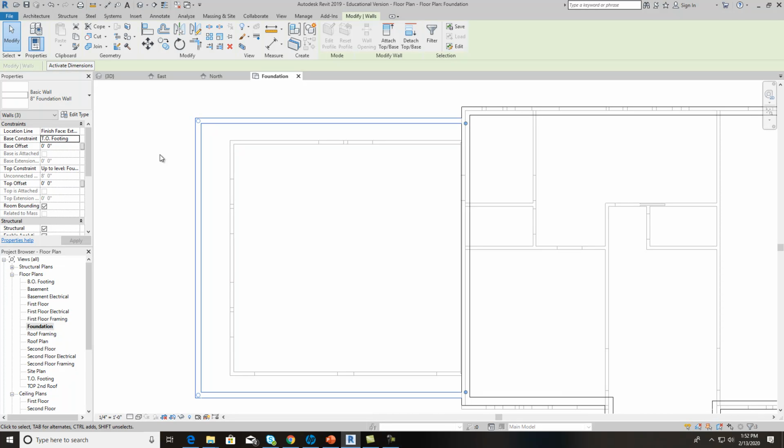So a lot of homes that are built in cold climates, or in a lot of major freeze-thaw areas, have basements, and the reason is that you've already got a footer that's that deep in a foundation wall, so you might as well get some extra space out of it. Even though this right here is not going to be a basement, it's going to be filled, the footer is that deep because of that, and that's why you see that. It could seem a little strange, but that's actually how that works.